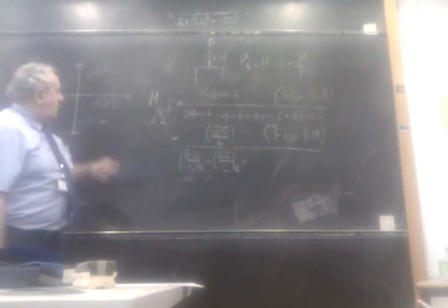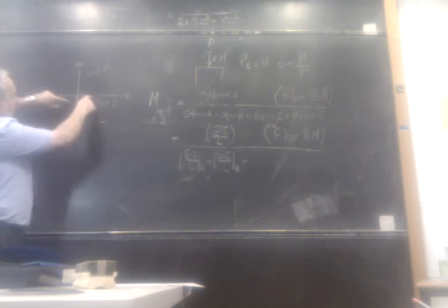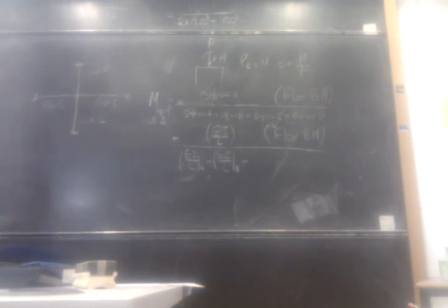And in the question it gives you the relative values: the elasticity of the floor slab is twice that of the walls. So E for that is twice E for that. Not quite practical, but it just makes the arithmetic easy for you. So the E values will cancel out.